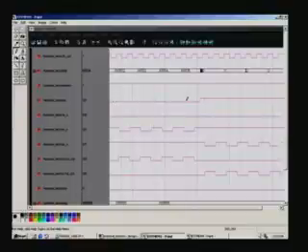We started writing for every location up to 65535 the data, that is 555, which is at the bottom, and now you can see that the write pulse has stopped here because write is over with 65535, and soon after that this address changes to 0, and also that RWN control changes to 1 here, so that we can start reading, or I mean this being 1, it is a read only mode.